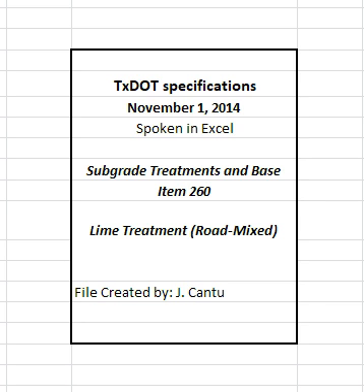4.3.2 Slurry placement. Provide slurry free of objectionable materials, at or above the minimum dry solids content, and with a uniform consistency that will allow ease of handling and uniform application. Deliver commercial lime slurry or carbide lime slurry to the job site, or use hydrated lime or quicklime to prepare lime slurry at the job site or other approved location, as specified.